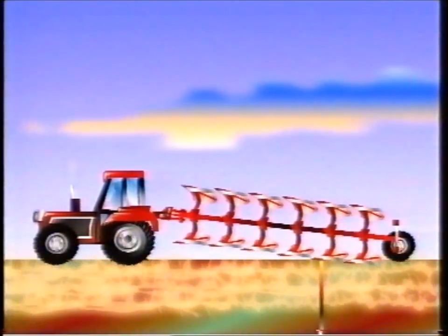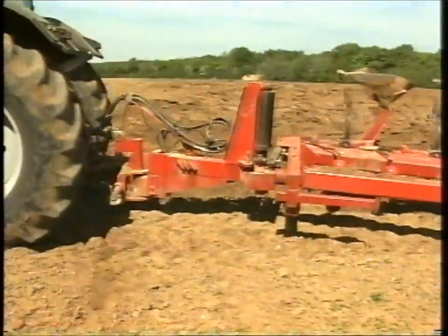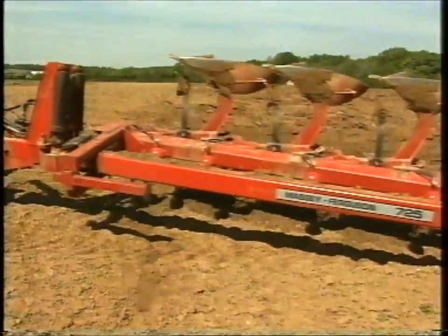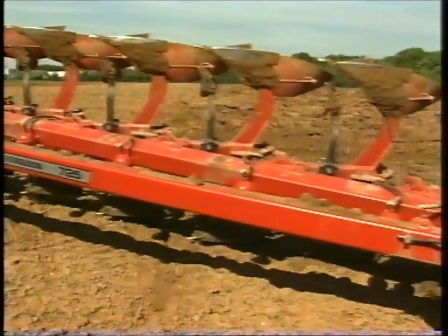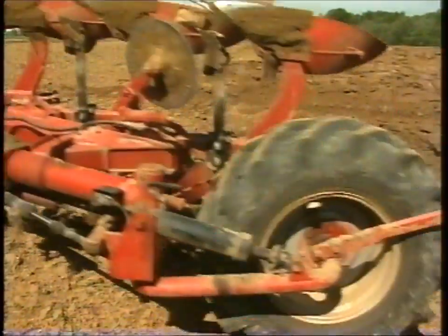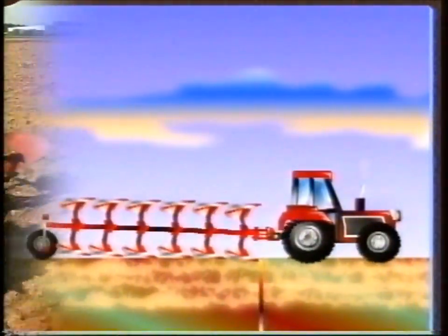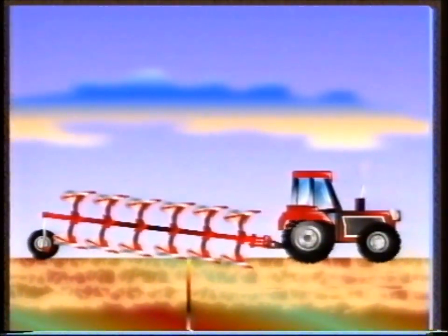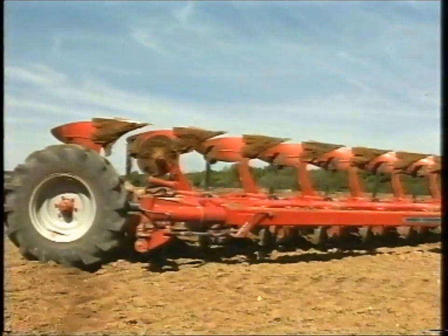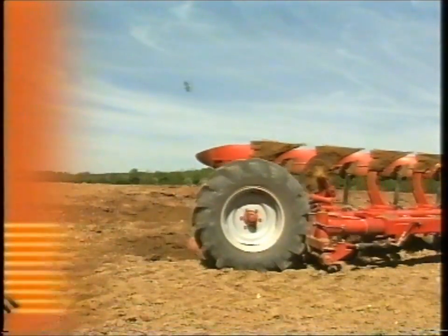The second important benefit is that using this screen, the dual control setting screen of Datatronic II, the operator can program in the effective length of the plough, so that furrow entry and exit is operated automatically. The operator needs only to press the ELC lift control button at the headland. Then, dual control automatically lifts the rear of the plough for him at the required moment.